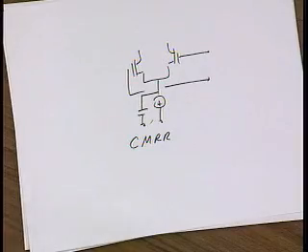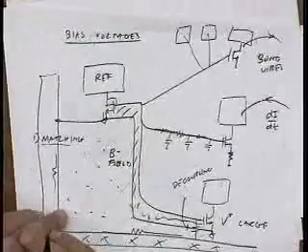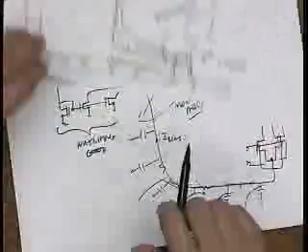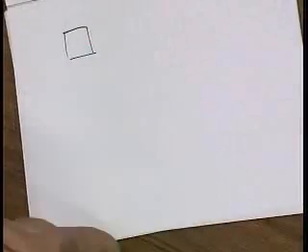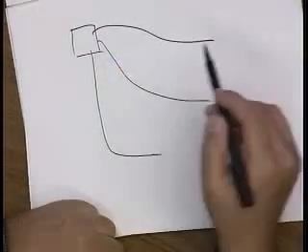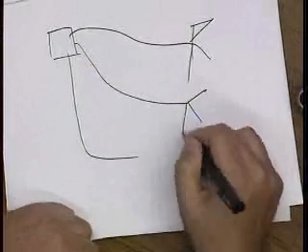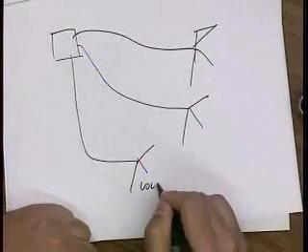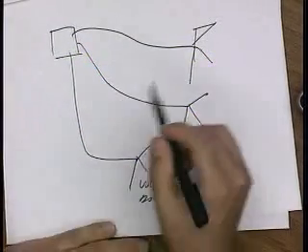It depends. Now, looking at all these issues, you see there is no magic bullet, right? There's voltage routing, it has some problems. There's current routing, it has some problems. Usually, a real chip uses a combination of techniques. And one approach, which is popular, is you current route globally and then locally voltage route. So this would be voltage routing, and this would be current routing.